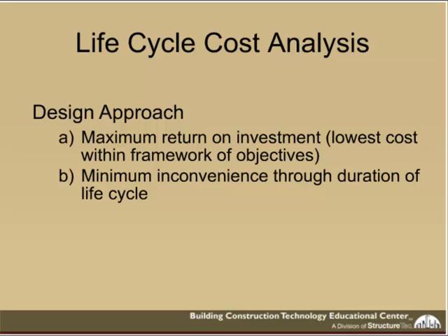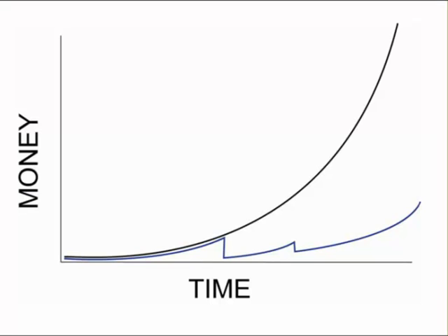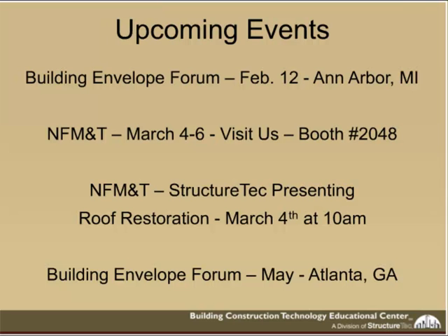So the balancing act between the three works together, and what you'll be looking at is that deterioration progresses no matter what. And so what you're looking at is at what point in time does the cost and the life of the structure and the frequency of interruption work out for you to do the repairs to bring it back as close to original construction before you let it go and let the deterioration do its normal thing again. If you're making the proper investments at the proper time, you can really manage the overall life cycle cost of that building. Right. Good stuff.